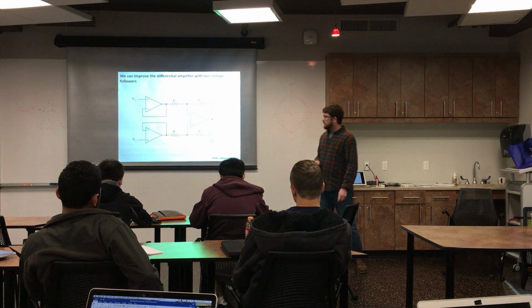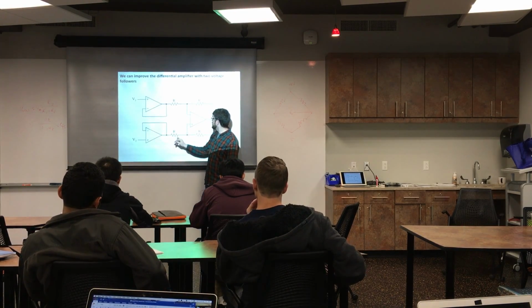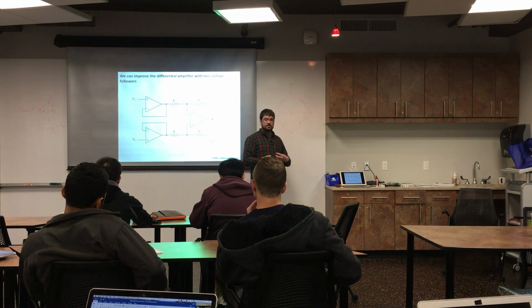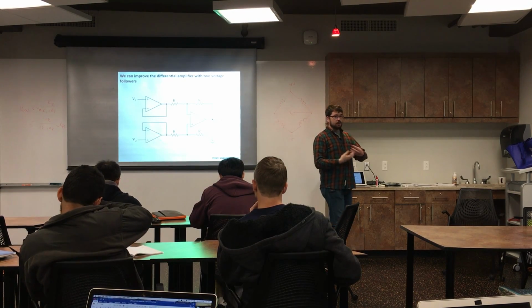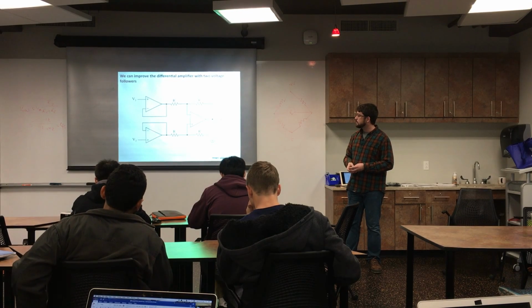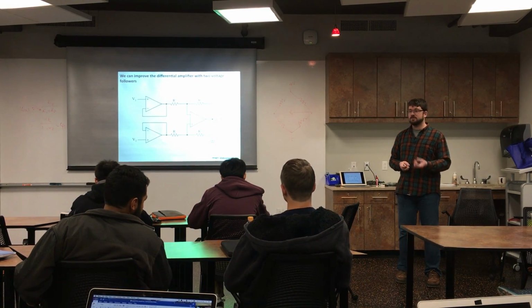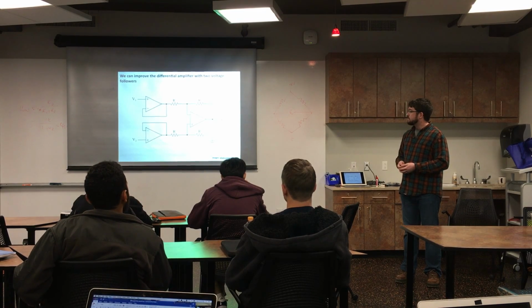You can do a little bit better if you set up two voltage followers. So you've got negative feedback on both of these. And then those dividers, because now at least you've got a very low source impedance for those voltage dividers and a very high input impedance for your signal, which you may not have had before, but you still have to have those precision trimmed resistors that can be expensive.